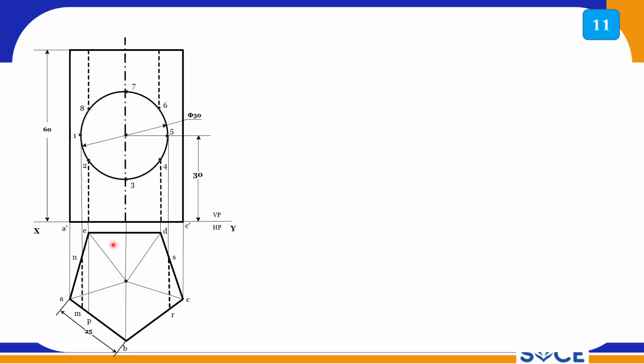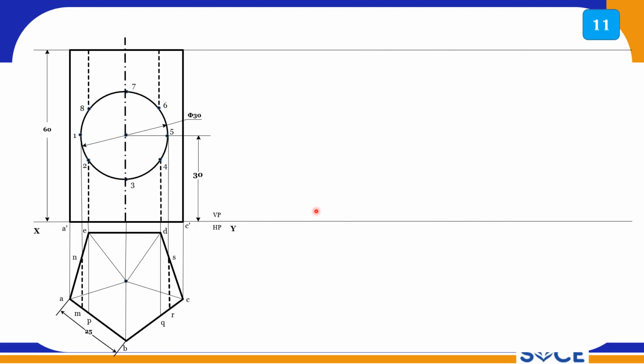And then you have a point. So this is point number 2, and this point should be marked here, and I am naming it as P. Similarly here I am naming it as Q. These points are purely used to measure the true length. So these numerals 1, 2, 3, 4 can be obtained along these parallel lines, and this P, Q, R, S on the surfaces we are going to mark, so it will be clear while doing this development.